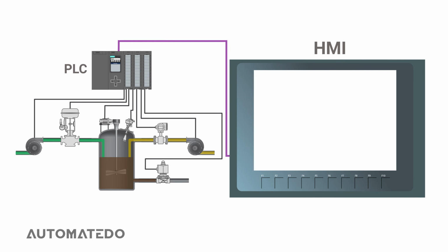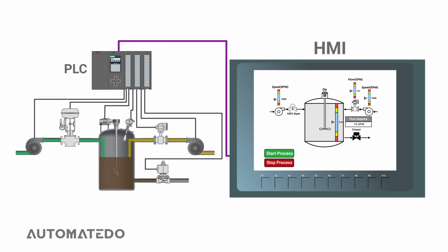The PLC will receive information from sensors mounted across the industrial processes in the manufacturing line and will start processing the collected data into logical combinations. As soon as the PLC provides real-time data directly to the HMI, the HMI is used to convert complicated process variables into information in a graphical way that may be used to take appropriate action.